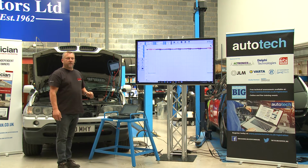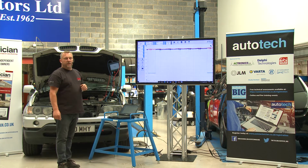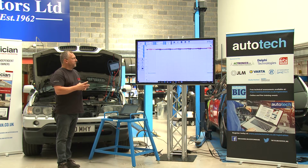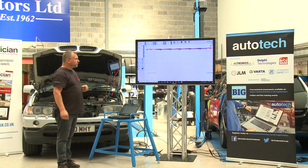Selecting the correct time base for the image that you want to look at using the PicoScope and then analyse is vital. Too long a time base and there's not enough detail, you end up zooming right in, looking at stuff, which isn't a bad thing. It's always better to start with too large a time base with a PicoScope and come in using the zoom than it is to start with too short a one and try and zoom out.